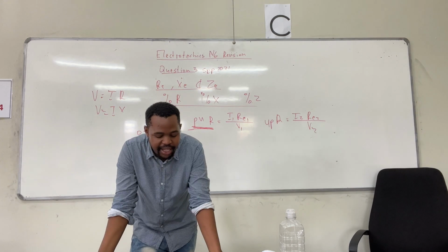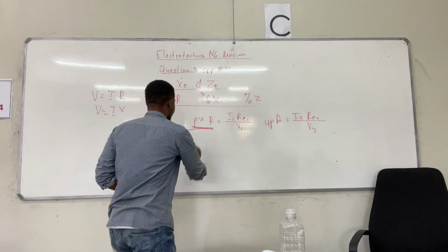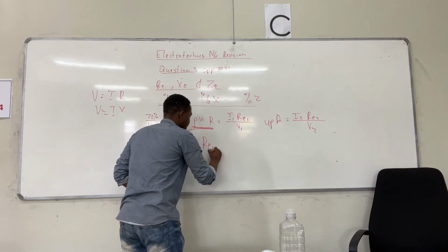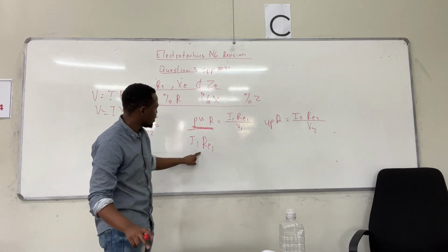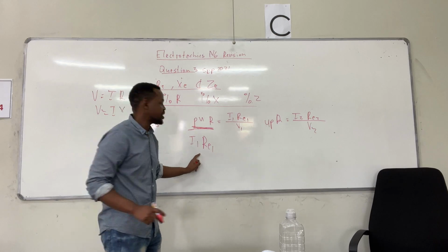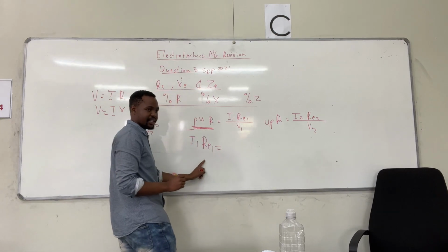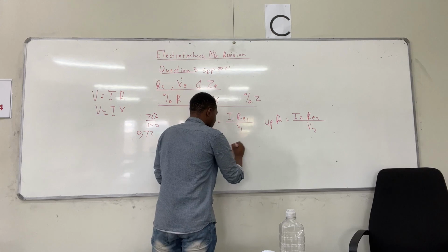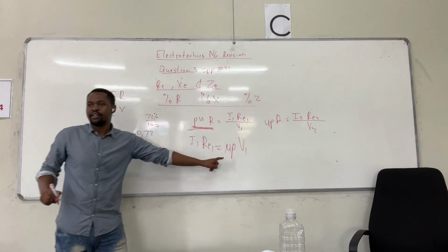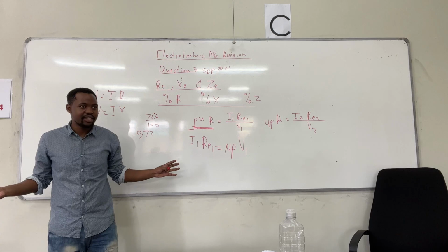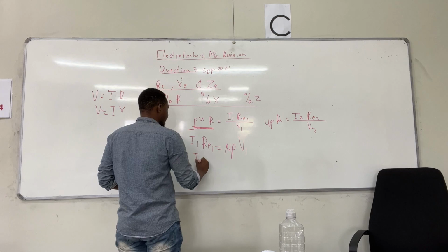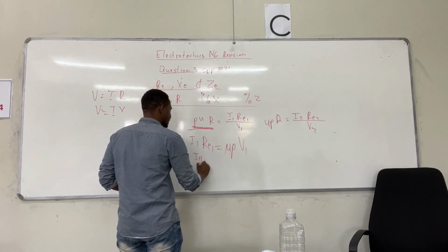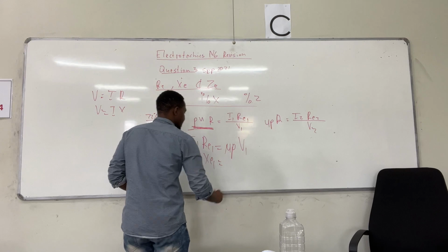If you look at those formulas, let's say you wanted to calculate the voltage drop due to the equivalent resistance on the primary side, referring to the primary side. So we multiply the per unit value by V1. We don't need to know the current. The same goes for the voltage drop due to a reactance.